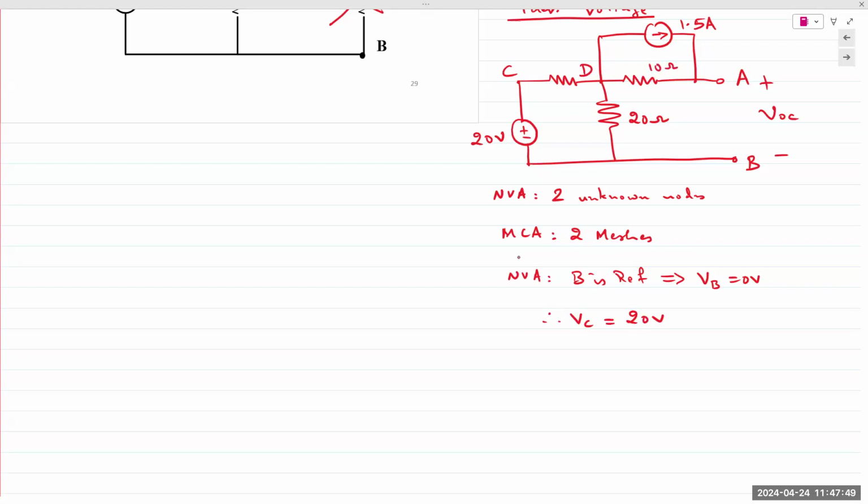Okay. So node voltage analysis requires me to assign branch currents. I'm going to assume a branch current for the supply, which goes up. It also goes to the 5 ohm resistor, splits between the two. This comes here. So these are not mesh currents. These are branch currents. Keep that in mind. These are currents flowing through each electrical branch, each electrical component. Okay, we call this I1, I2, and this is labeled as I3. These are the currents that are flowing through each one of those resistors.